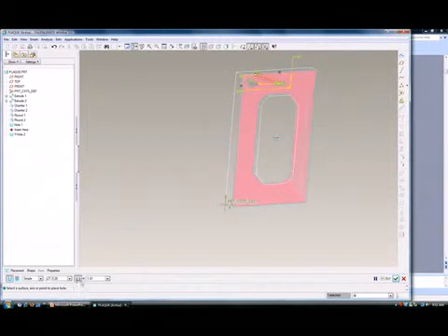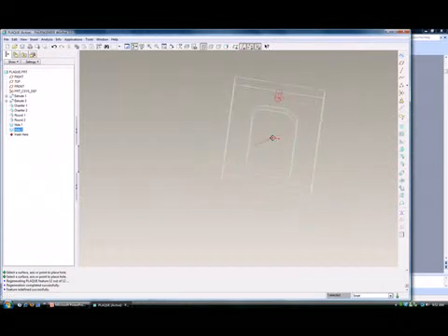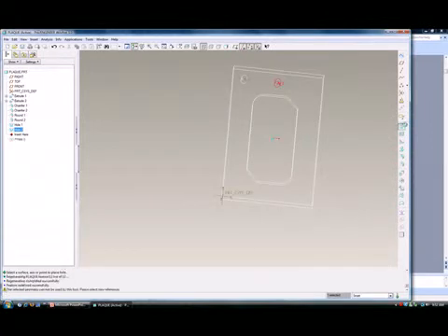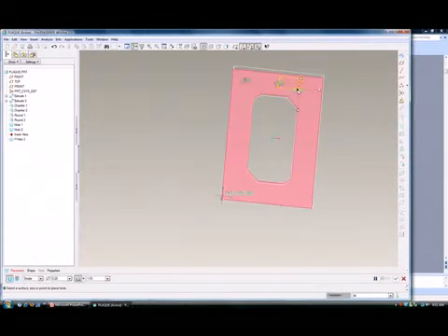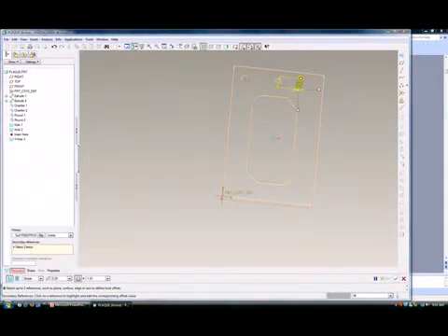And then I'll go to, oh no, draw all the way through. Okay, this looks okay. Now I hit the middle button. Okay, repeat this for the third hole. Same thing, hole, select the surface, placement, click here to add references, select two edges.